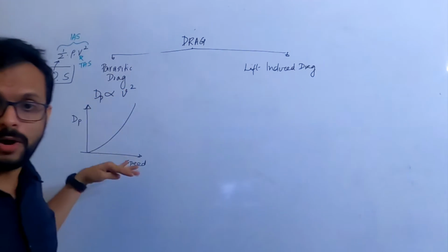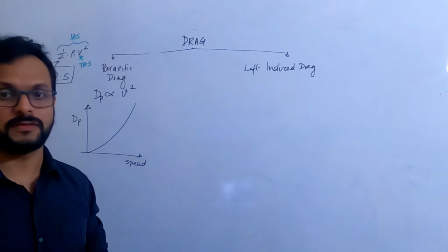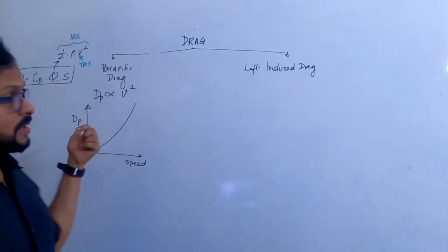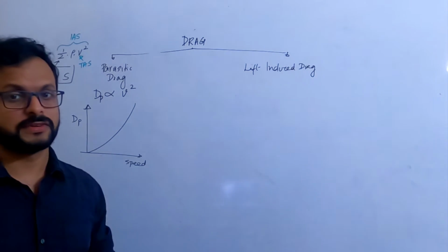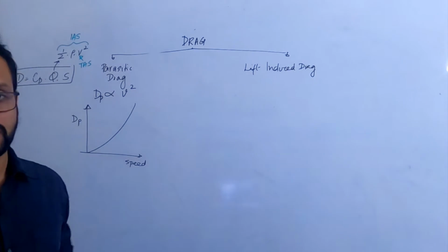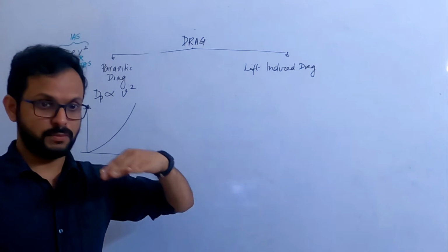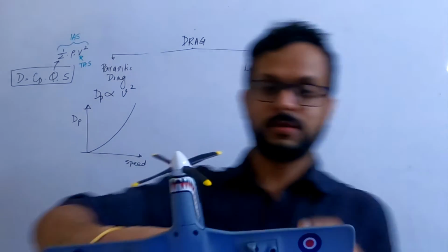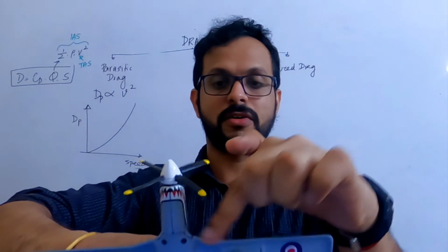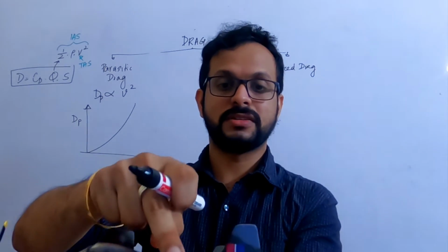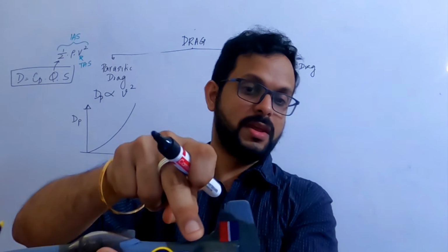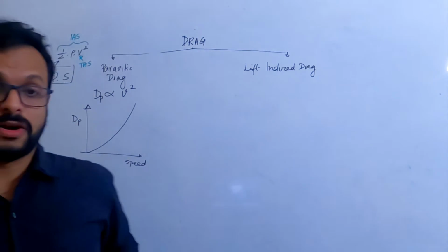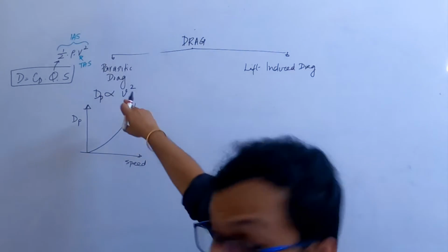Now we also spoke about lift induced drag. One more thing, we also spoke about how to reduce parasitic drag. It's mainly by cleaning the surface, making sure it's free of ice, dust, dirt, etc. That's a pre-flight thing. And we can reduce the skin friction or form drag by streamlining the surface, which is more of a manufacturing point of view. And you can reduce the interference drag by smoothing the surfaces, by making them more curved, as I showed you in a model yesterday. In this particular aircraft the wing is curved here and not very abrupt. It's much more evident at the tail here. You can see how it's curved rather than abrupt, so this will help reduce the interference drag. That is how we try to reduce the parasitic drag.